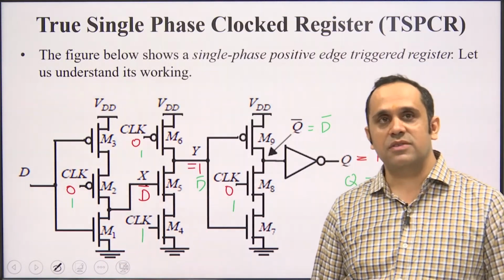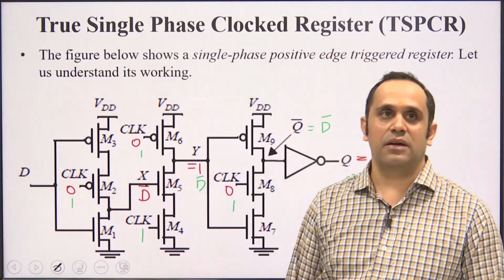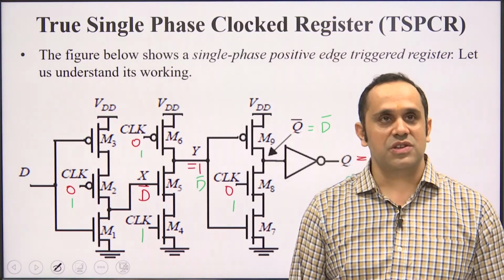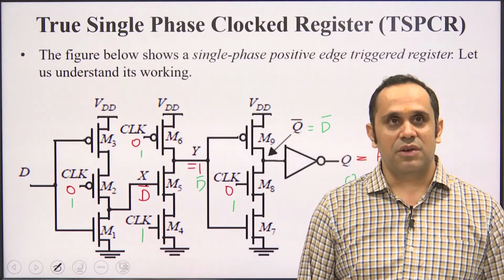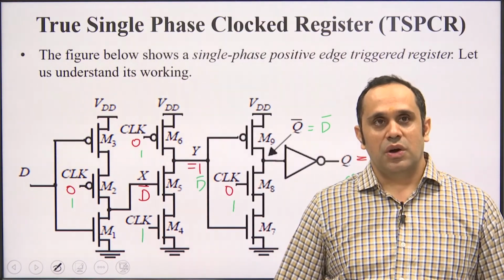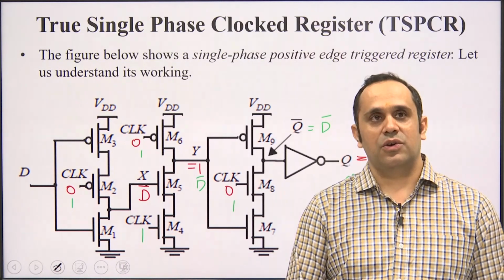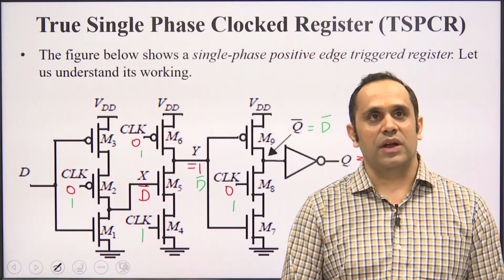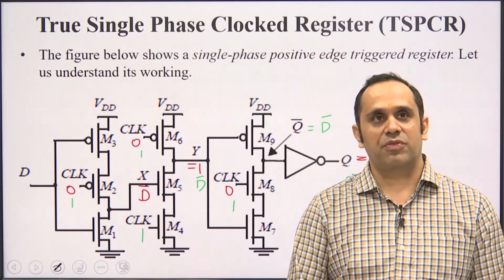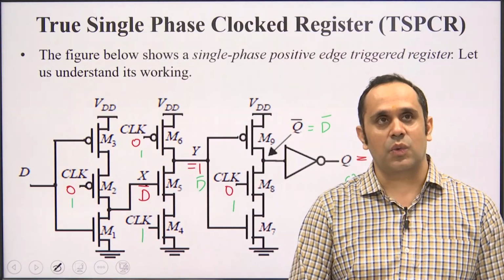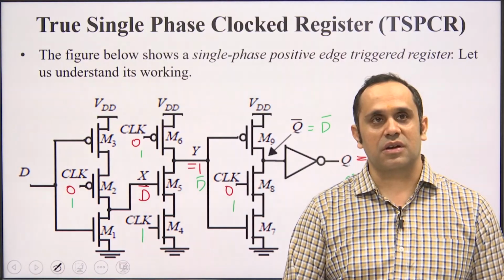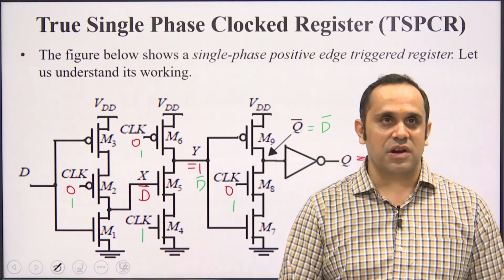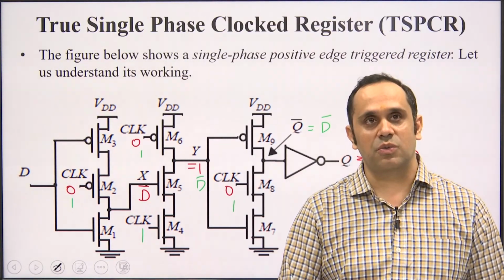So, just to summarize today's lecture, we have come towards a good stage in the design of dynamic CMOS sequential circuits, where we have seen that to reduce the requirement of area, the amount of transistors or silicon area required, we can switch from static to dynamic CMOS sequential circuits. You can implement using pass transistor, but there is the problem of threshold voltage.